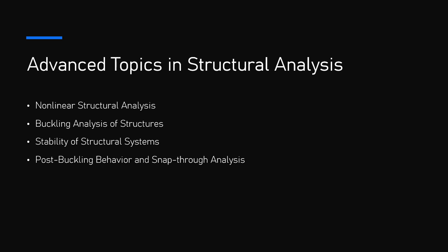Viscoelasticity involves both elastic and time-dependent viscous behavior. It is important in materials like rubber or polymer-based composites, where the structure exhibits both elastic and time-dependent responses. Fracture and damage. Materials may experience cracking or damage that alters their stiffness. Damage models help simulate the propagation of cracks and the degradation of material properties.